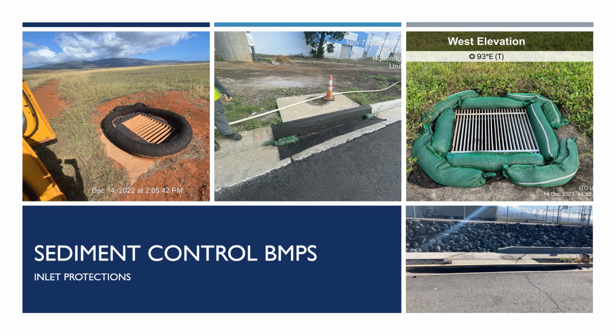Inlet protection is important to protect storm drainage systems and receiving waters. Examples of this BMP include filter fabric secured to a drain inlet, filter socks or gravel bags along a drain inlet opening. For inlets receiving a heavier amount of stormwater flow, a filter insert, such as a witch's hat, can be utilized. Inlet protection is the last line of defense and used in conjunction with other on-site BMPs.